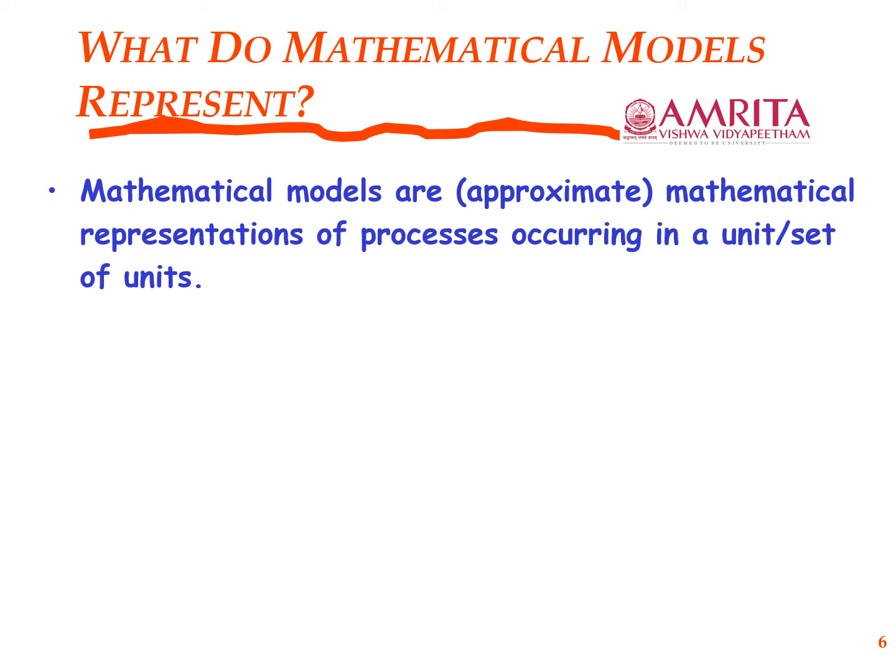However, it ensures that there is a sufficient amount of liquid in all the stages, and also, in distillation processes such as that of crudes, since no product is a pure component, they are all cuts, right? So it ensures that there is a sufficient amount of the distribution of the various components that are present in a cut by its pump arounds.